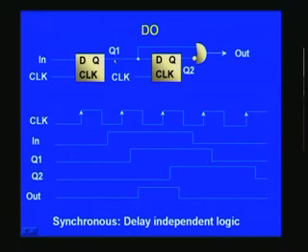And this in turn is applied to another flip-flop, and that output also you can have a look. That's also a delayed output of this particular Q1, and once again we get it here in this fashion. So ultimately we get a pulse like this, and you notice that the actual width of this pulse is the width of this clock period. Except that there is a delay here owing to the delay between clock and Q, because internally there are circuits, and any gate means a delay. So that is what is getting reflected here finally, and this is how we solve for a single pulse if you desire just a single pulse to be created.